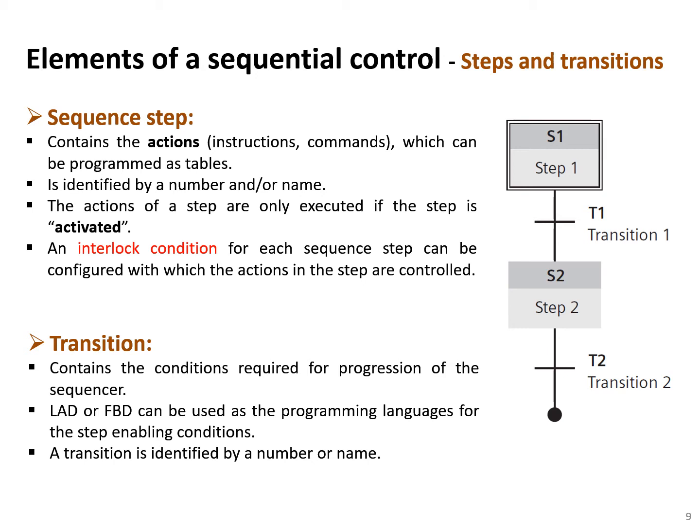An interlock condition for each sequence step can be configured with which the actions in the steps are controlled. Okay, so these interlock conditions are extra conditions inside the step. In most cases we don't use these interlock conditions, at least for the purpose of this course.